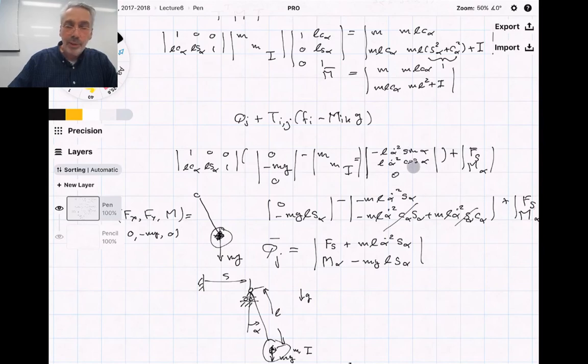Here we have the convective accelerations. That's exactly how I've drawn them in the figure. Remember? Acceleration pointing in that direction, and it was alpha dot squared times L. That's exactly this thing. In the x direction minus, and in the y plus. So this transformation projects this acceleration on our degrees of freedom. That's the whole thing where I try to say it's a projection method. It projects our equation of motion on the generalized coordinates.